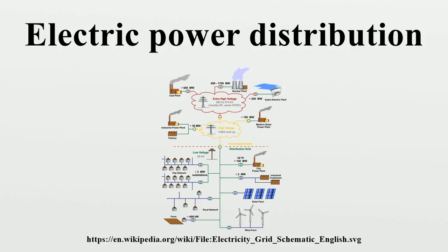Rural electrification systems, in contrast to urban systems, tend to use higher distribution voltages because of the longer distances covered by distribution lines. 7.2, 12.47, 25, and 34.5 kV distribution is common in the United States; 11 kV and 33 kV are common in the UK, Australia and New Zealand; 11 kV and 22 kV are common in South Africa. Other voltages are occasionally used.